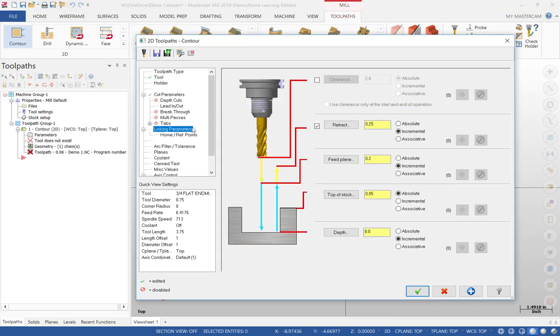Link parameter, that's where the major setting is in here. Remember, we have the clearance plane, retract plane, and the feed plane. So these are the settings in here in these two setups. We want to override it so that we can actually adjust this number. What it will do is have the tool coming in, let's say this one, clearance.